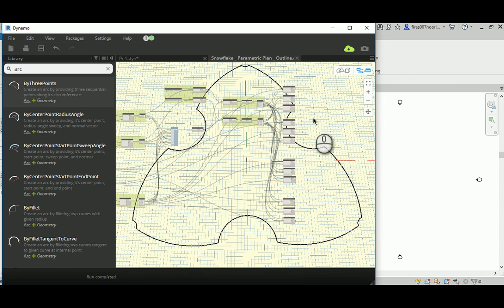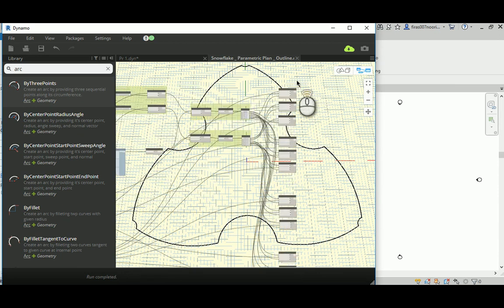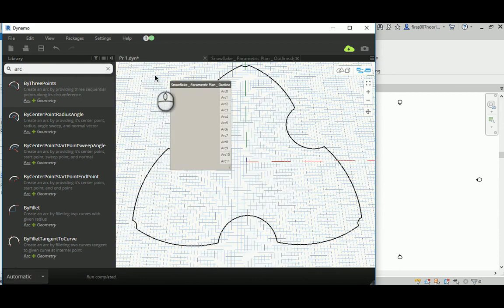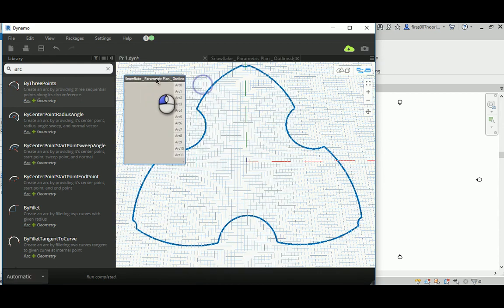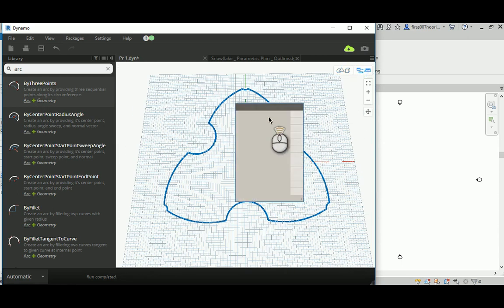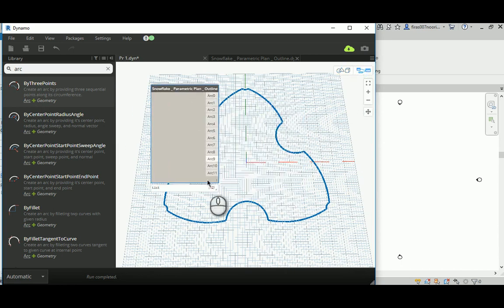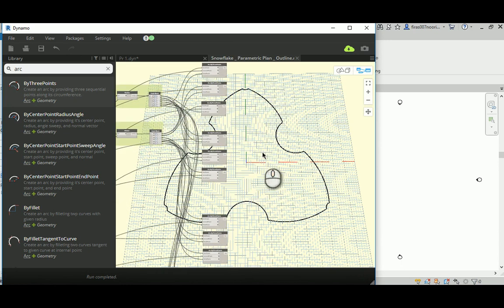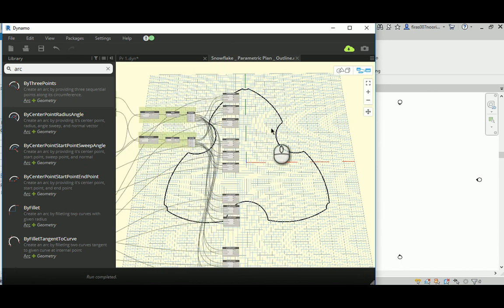But the problem is this: I'm just going to save, and if you go to Dynamo, the project we are just placing that in, now things are getting more interesting, huh? See, that guy you placed has lots of outputs, and all of them are just separated lines, and we don't want that. We're supposed to have a continuous polyline in order to make an extrude or loft or whatever. It doesn't work to have separated entities.